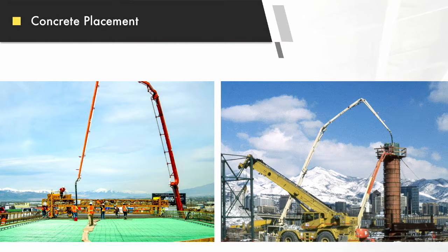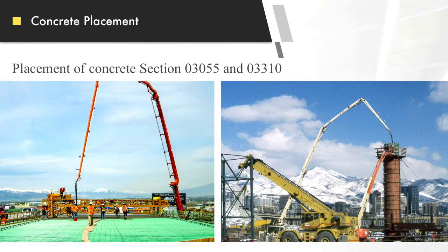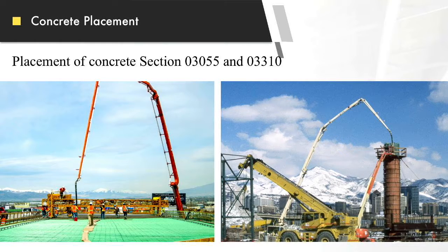But on decks, abutments, most times on bent caps, they have enough shoring up there that's big enough and wide enough. You can use their man lift to get your equipment up there. You have enough room to be out of their way, test it right at the point of placement. And there's the sections on placement.